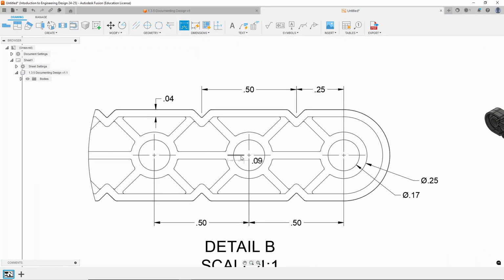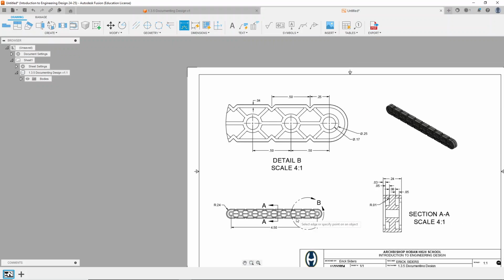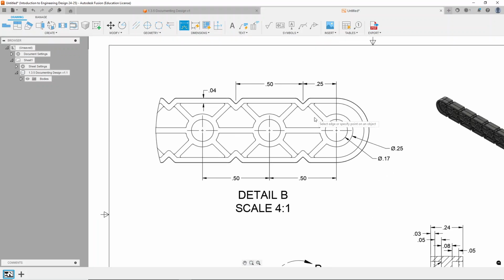So now what this is telling us is that these holes are 0.5 inches apart, and then these little triangle indents are exactly between them since they're 0.25 inches away from the center of any circle. We've only dimensioned these few circles, and there's more on here. So we're going to add some indicators telling us that this is a continuing dimension. It is repeating down the line.